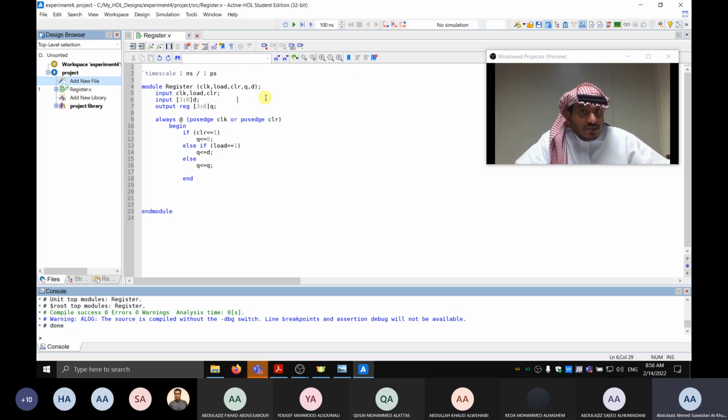I want to change it to 16-bit. You can use Input N also. 0 to 15. Yes, I will change both of them from 15 to 0. Don't say 0 to 15, say 15 to 0, please. Okay, so 15 to 0, 15 to 0, I make it 16-bit. Very easy to change. If someone says 32, you just make 32 bits, 31, 31.